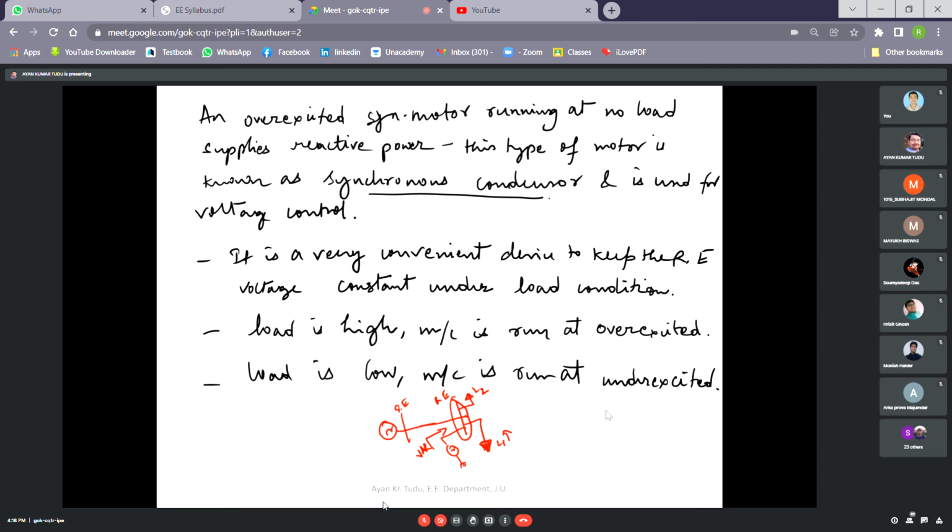No sir. Okay, so we'll be finishing our class with the limits of overexcitation and the limit of underexcitation for a synchronous generator. Can anyone tell what is the limit of overexcitation for a synchronous generator? Overexcitation means EF is greater than the terminal voltage, right? When does that happen? When the rotor flux, the amount of field current, is higher. There is more field current in the system, because EF is produced by phi F, and phi is proportional to IF. So if IF increases, phi increases, and EF increases. So overexcitation is due to the increase in the field current, correct?